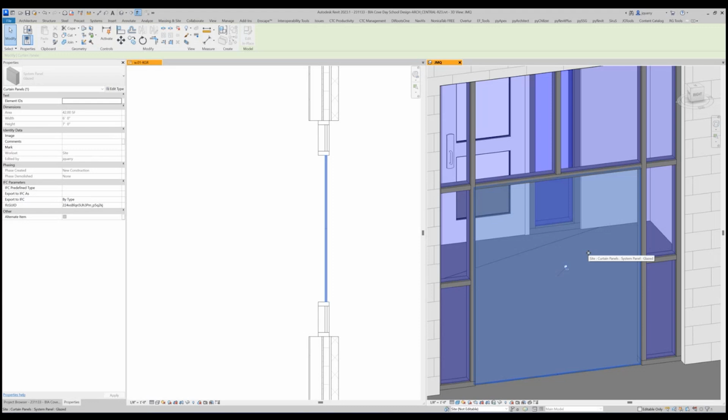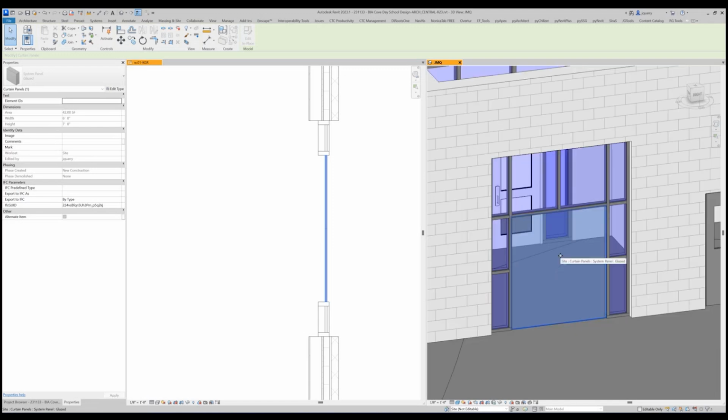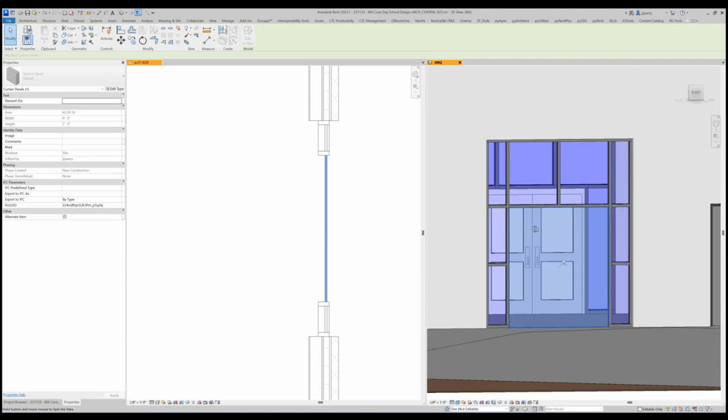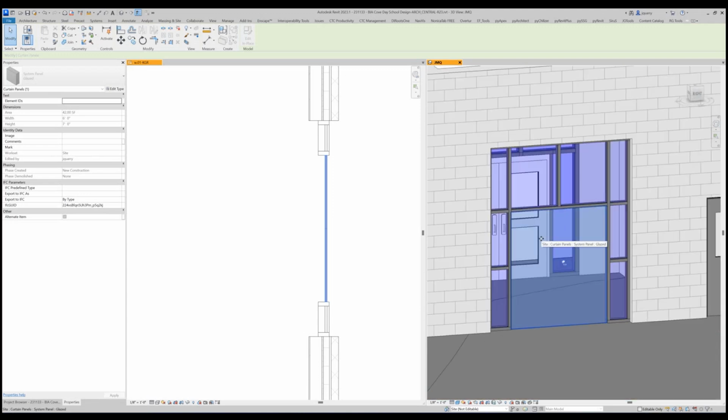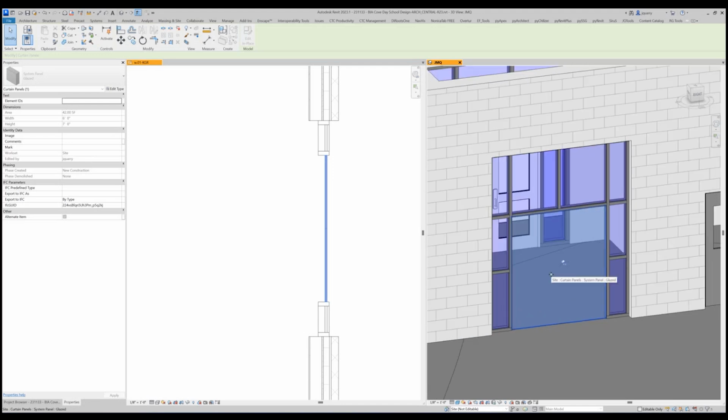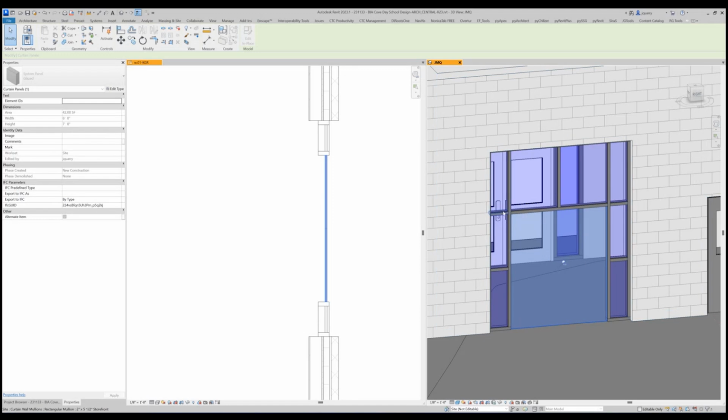Now, I was trying to get to 7'4". Is that where you want it? Are these 7'4" doors? I was just considering the size of the header. No, you've got a good point, because 7 foot isn't a masonry opening number. Our doors will be 7 feet tall, but with a 4-inch head, our masonry openings will be 7'4". Okay, that's great to know, because another thing I'm going to show you is how to change the size of these guys. Let me look at the elevations. I would assume they're going to be 7'4" with 4-inch heads. Sometimes they'll do 7'2" doors with 2-inch heads. That's the newest craze.